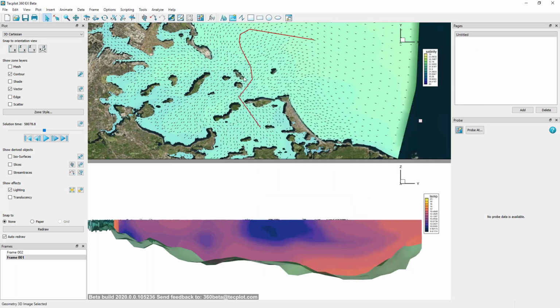So the next thing I want to do is show the information along the path of this polyline. Unfortunately, for this data set, the variables that we have that are spatial variables are x, y, z, and longitude and latitude. But this polyline doesn't really follow any of those variables cleanly. But what we can do is calculate a new variable that is effectively the length or path along the polyline, and we'll plot along that rather than one of our predefined variables.